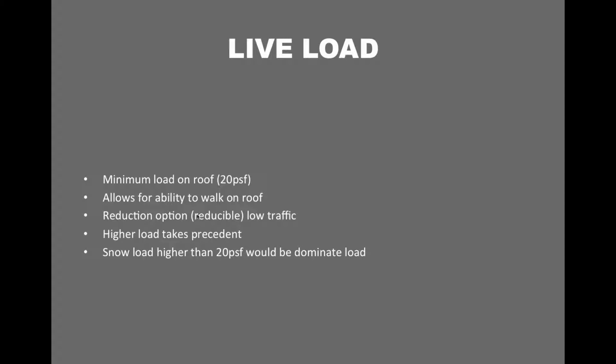In most places, they will allow you to reduce that live load if you don't anticipate having frequent traffic on your roof. In other words, if you aren't going to have a lot of people up there walking around, which is 90% of buildings, they will allow you to reduce that, and that reduces the roof load down to 12 psf.